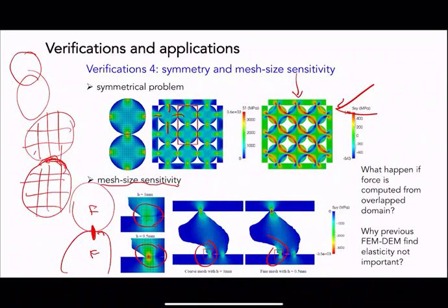However, if you have a mesh like what I show here, your integration of the vertical stress is based on the Gauss point stress. As the Gauss point is some distance from the singular point, the stress here is finite, and hence the external force you compute from the mesh would also be finite.